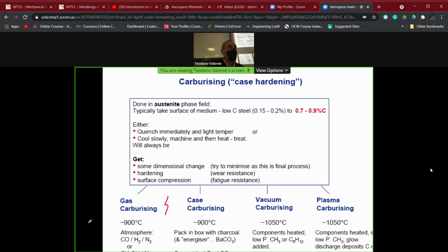But essentially, it is based on the solid state diffusion of carbon, which we are able also to model, because remember the Fick law of the solid state diffusion, which we know also in terms of mathematical solution to make some calculation, and the diffusion of carbon to a certain depth, which can be calculated and controlled from the top of the surface, give rise, in this case, to the presence, due to the size of the carbon atom, of carbon in the interstitial elements.